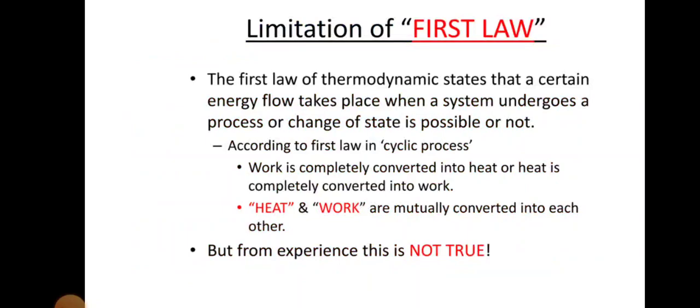The limitation of the first law. The first law of thermodynamics states that a certain energy flow takes place when a system undergoes a process or change of state, but not whether it is possible or not. According to the first law, in a cyclic process, work is completely converted into heat or heat is completely converted into work. Heat and work are mutually convertible into each other. But from experience, this is not true.